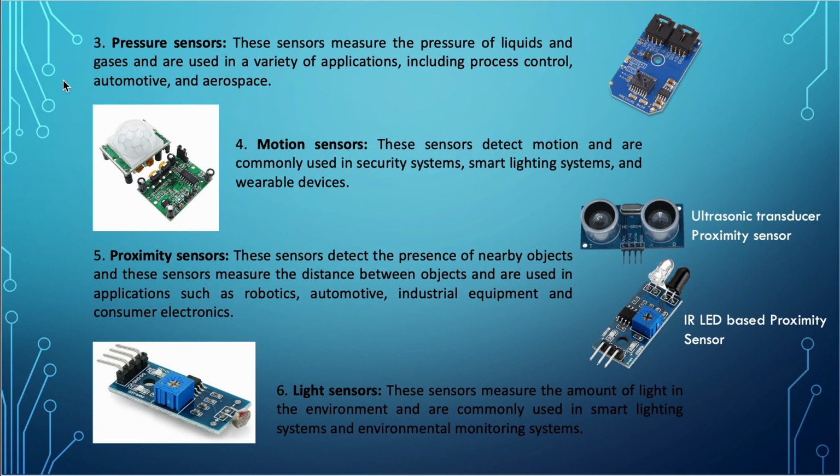pressure with different potential, with different characteristics. So the general understanding is there are sensors to measure pressure, gas or liquid. It is up to the engineer to find out the specifications, to find the range, find out whether it's a liquid or a gas, and then select the correct pressure sensor. Give an example. Another example would be,